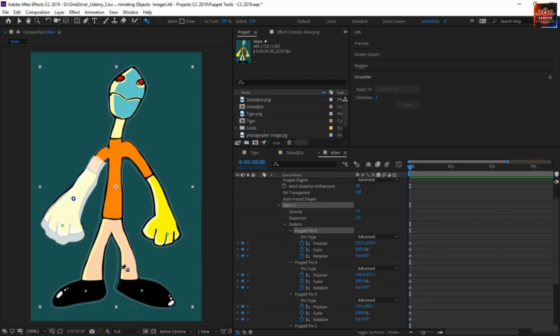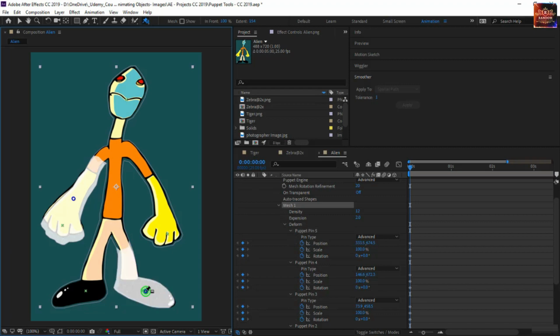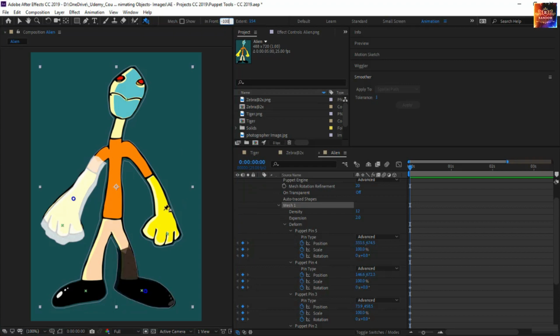Remember guys, you can see the mesh here with the line. I will click just over here. Now it's white, which means it's positive. Let's make it negative, minus 100%. You notice the color has changed to black. So in front, or towards the front, or positive in front is white, and negative in front is black. And maybe I will move it a bit for the extend.